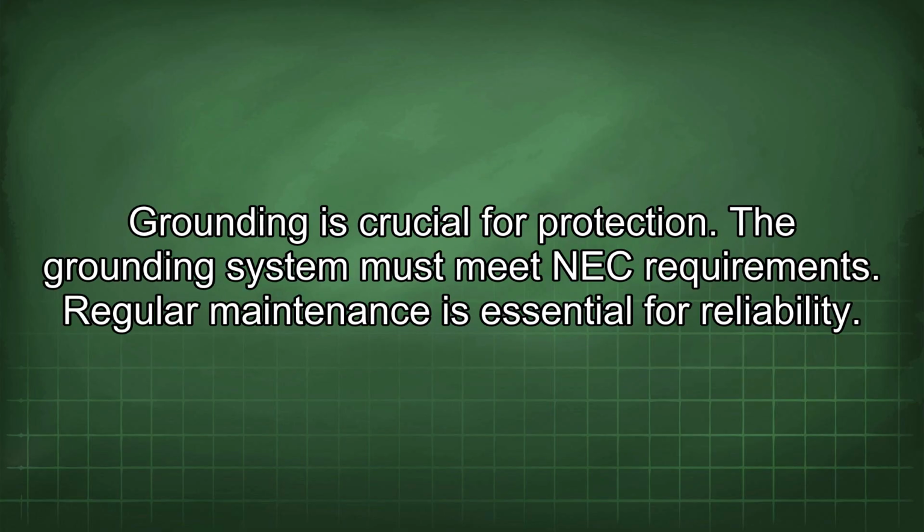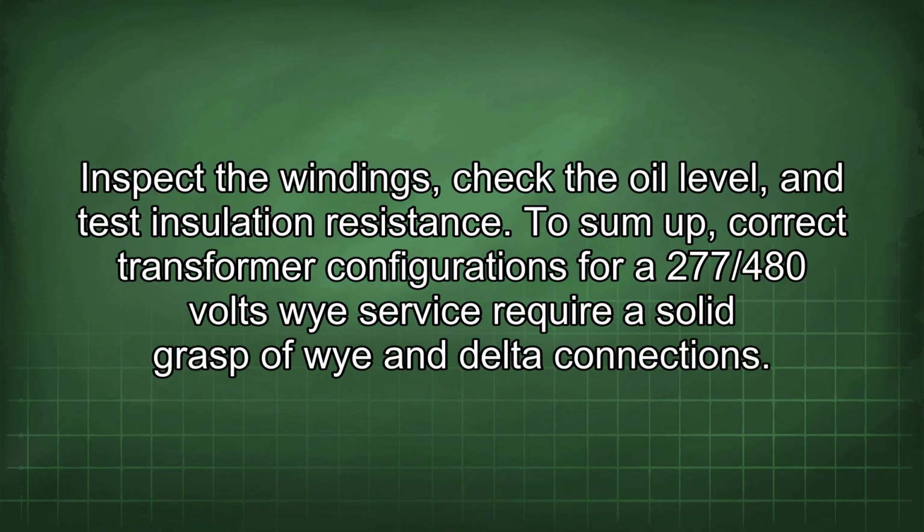Grounding is crucial for protection. The grounding system must meet NEC requirements. Regular maintenance is essential for reliability. Inspect the windings, check the oil level, and test insulation resistance.